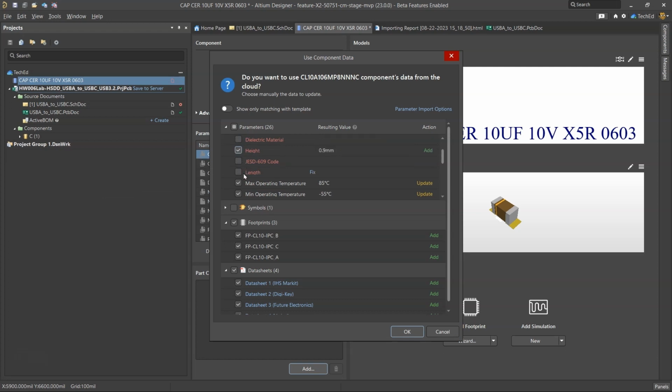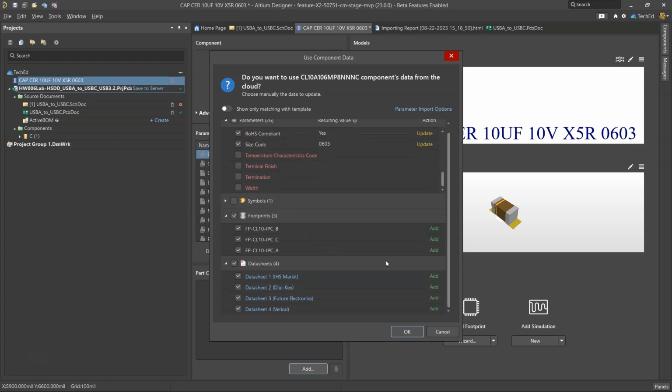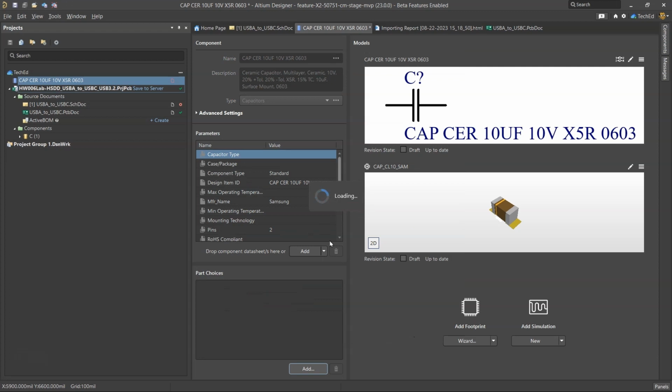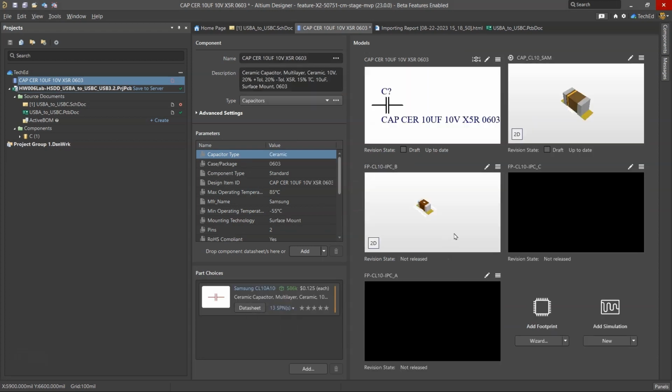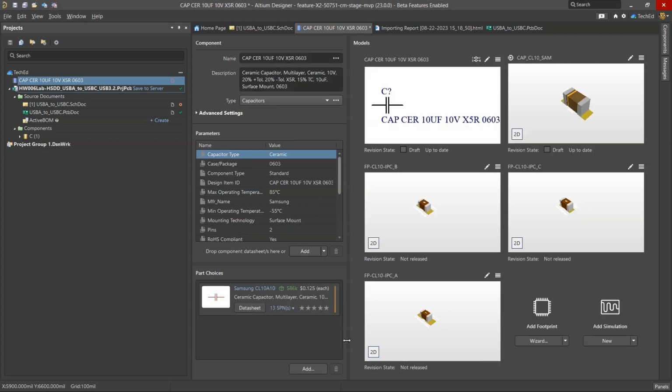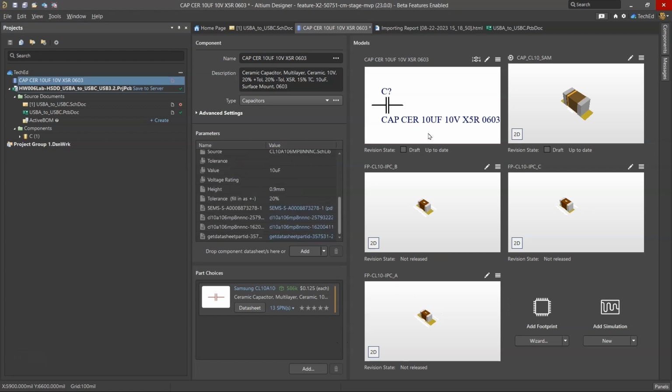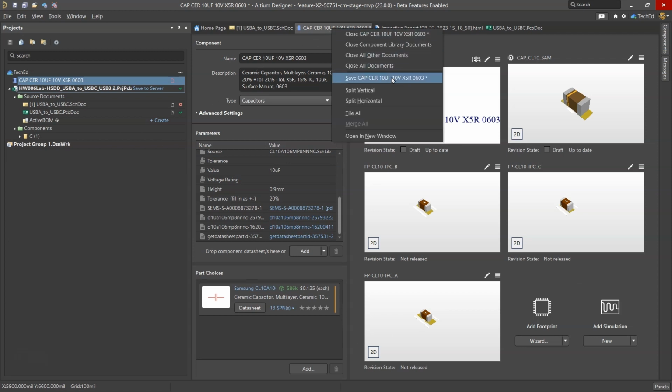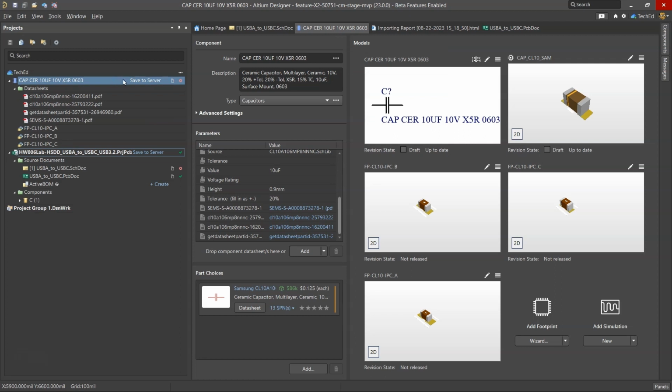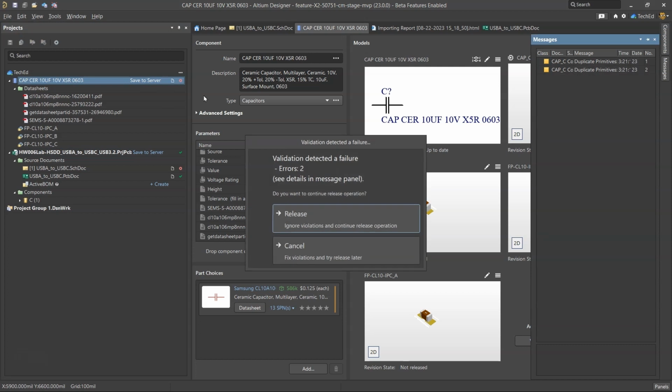The height, yes. The length, it's not too important, right? You got your symbols if you want to add them. I'll just go ahead and go with these options here. Then you get a whole list of things you can add to your device, your component that you pulled from the local library. So you don't need to add all of these locally, manually, and all that stuff. You can just get something quick and fast from Octopart or from Ultra Librarian and upload it, save, make your modifications, customize it the way you want, and then save it to server release.